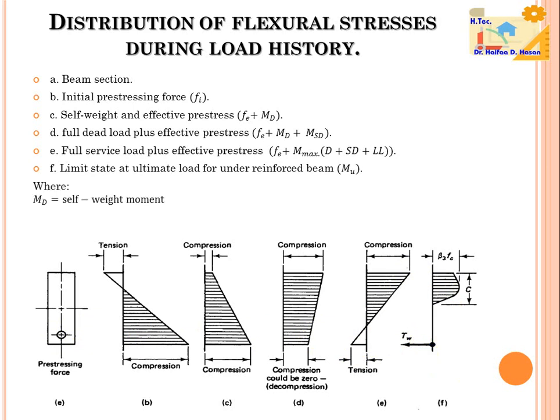Where MT equals the self-weight moment, and here MSD equals the additional superimposed moment, the weight of the slab concrete, and also the additional loading.